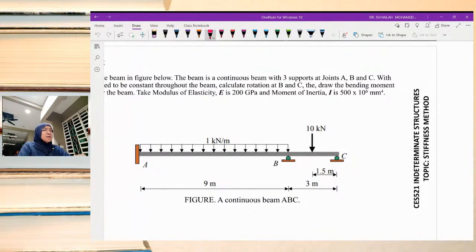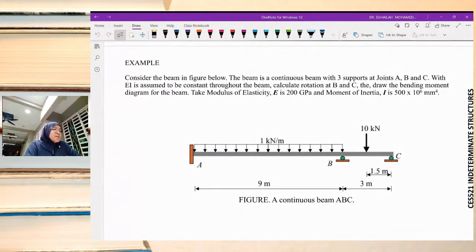But in beam analysis, beam and frame as well, for the stiffness equation we have to use Q is equal to KD plus Q naught. In truss we have Q is equal to KD, where Q is nodal forces, D is nodal displacement, K is structure stiffness matrix, and now in beam we have to consider Q naught.